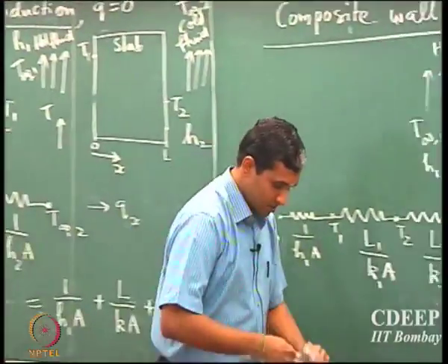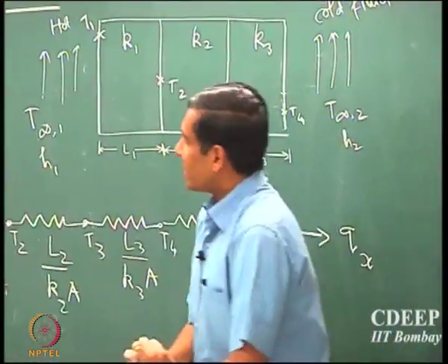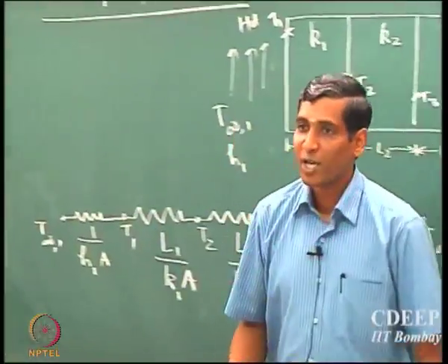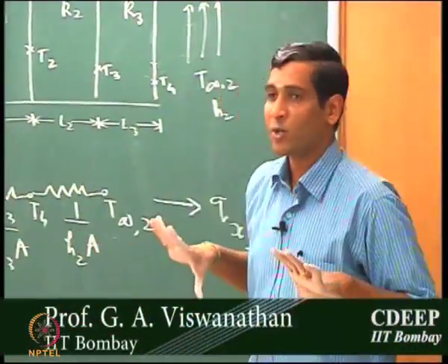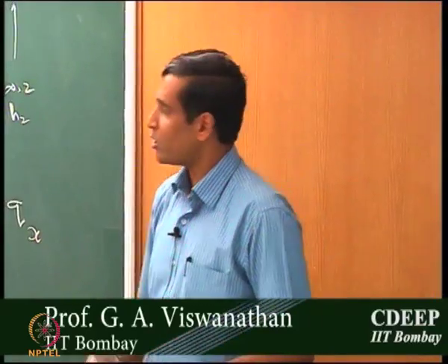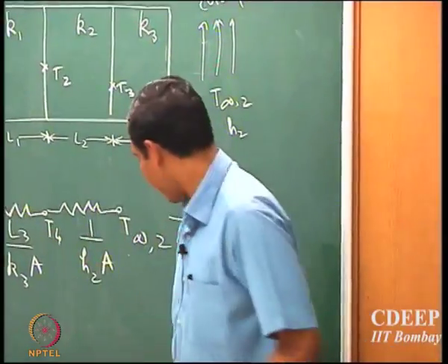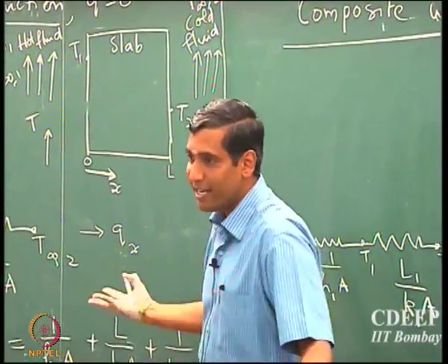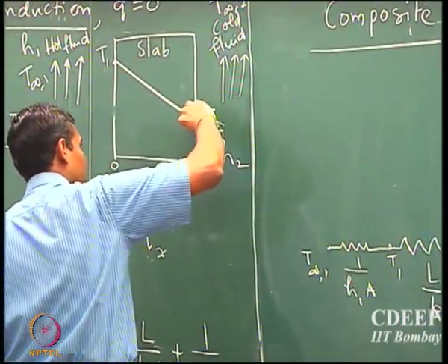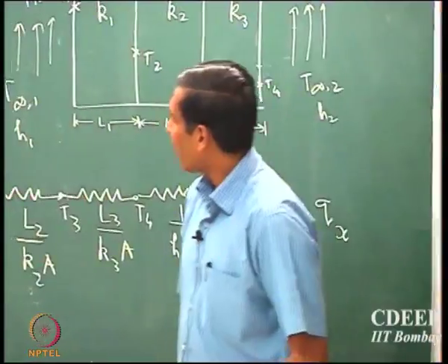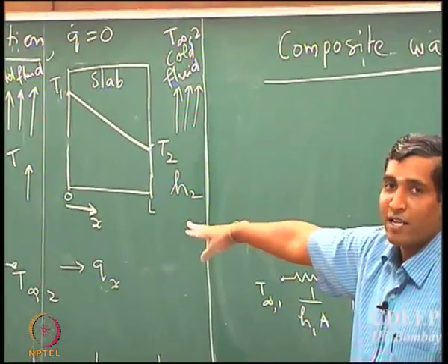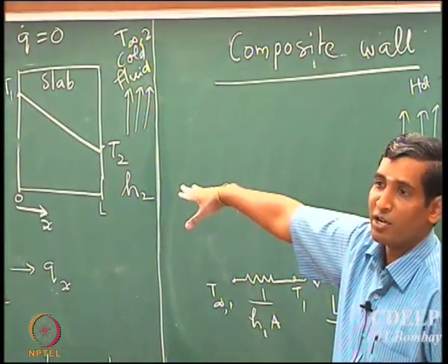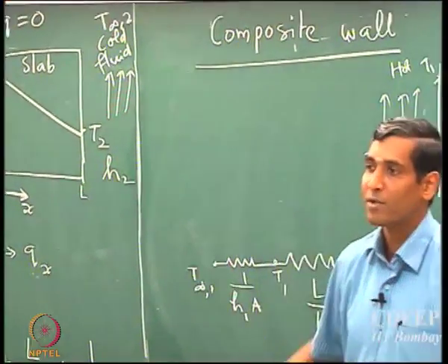Okay, so I think it's a good point to stop. In the next lecture, we said we assume that the cross sectional area is constant. So we're going to start with a specific case of a varying cross sectional area system, and we're going to see how the equations are going to change and how the temperature distribution is going to change. By the way, one important point before we close: what will be the temperature distribution in this slab? It's linear, very obvious from the expression. So it's a linear temperature profile. And what will be the temperature profile if there is a varying cross sectional area, and we look at other geometries? We looked only at Cartesian coordinates here. We'll start looking at radial systems and other coordinates. Okay.